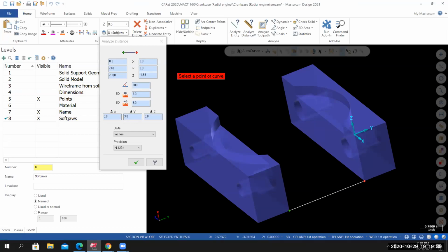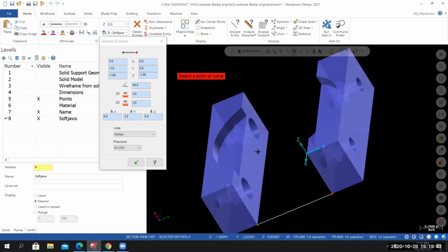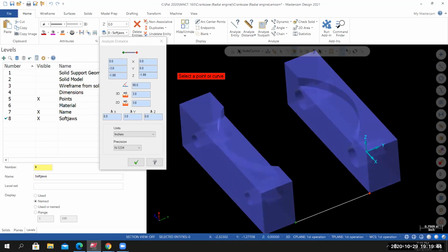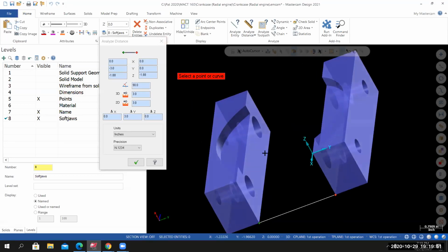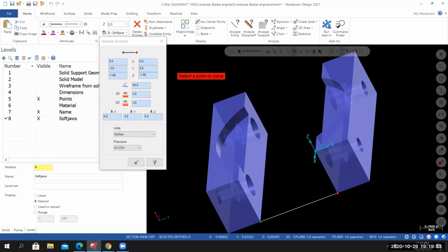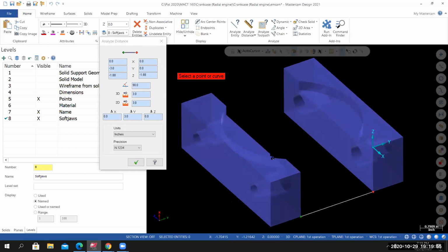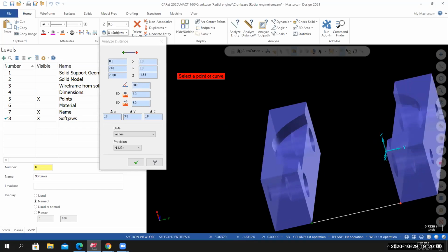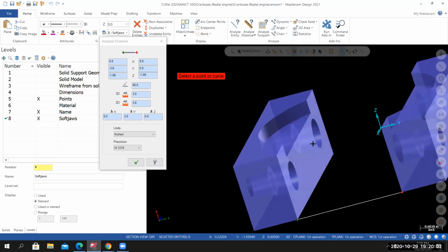So what I would need to do is find something that's 3 inches, place it between these two jaws, and then tighten down on that 3-inch piece of material. Or what I would use in this case, I would take a 1, 2, 3 block, take the 3-inch length of it, place it in between the jaws, and then tighten down on it. You just want to make sure that the top of the block, or the top of the material, is below this edge right here, because when we're cutting out this profile, anything that's sticking up too high will also get machined. Does that make sense?